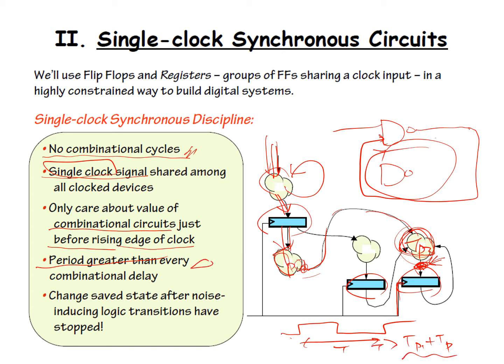This is very important. Some students, without this notion, design a digital circuit where the propagation delay exceeds one clock period. In the simulation, it looks like it works as you expected, but in a real system, such a delay cannot be guaranteed. It will vary for different process, voltage and temperature. So never let your propagation delay exceed one clock period. This must be a golden rule for single clock synchronous circuits.